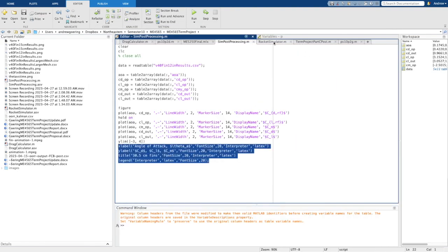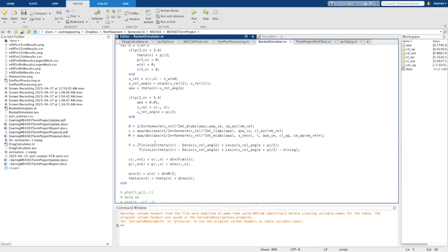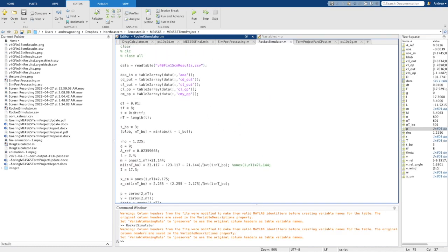And so this data right here, and then interpolated values between these data points between 0 and 10 degrees, are what's used as the input to this simulation right here, which uses an explicit Euler solver down here that's being updated down here. And you've got velocity, 2D position, and then angular velocity, and then angle, like the yaw angle of the rocket. So we can run this.